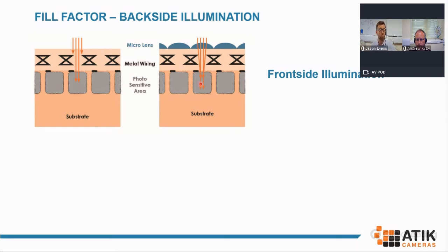If we move on to the right-hand image, we can see the addition of microlenses. These are available for both CCD and CMOS sensors, and as the name suggests, these are minuscule optics that help to focus the incoming light. I almost think of them sometimes as small contact lenses, helping to shape and focus and make sure the light is going to the right place.